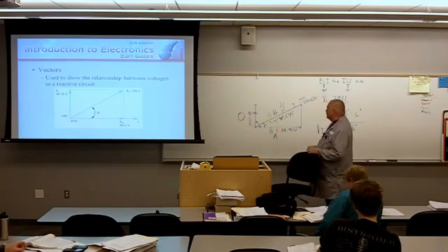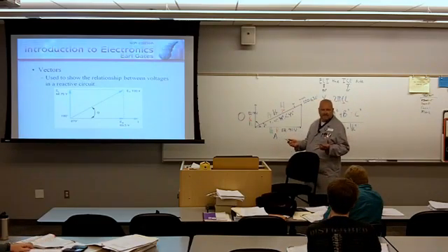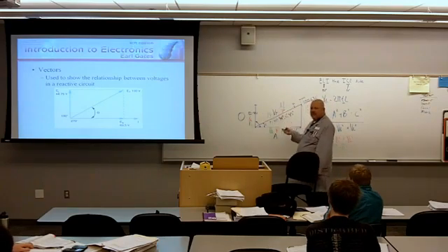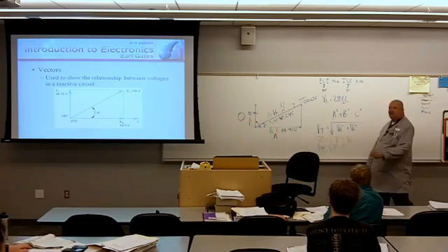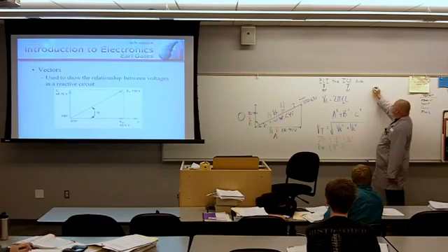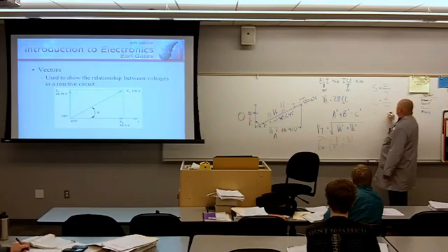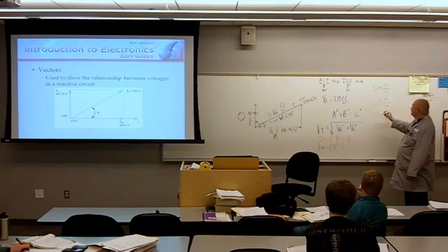The only other thing that you need to be able to solve for in a series circuit is angle theta. Angle theta. And if you know any two sides of the right triangle, you could solve for angle theta. One of the phrases that pays, the one that I always remember, it's silly, don't laugh, got me this far in life, right? Some old horse came a-hopping through our alley.